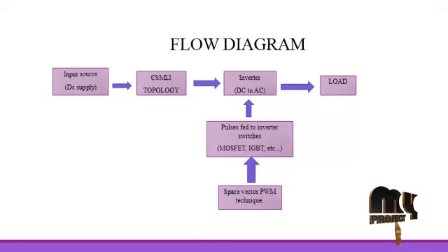Another main parameter in calculating the total cost of the inverter is the maximum amount of voltage blocked by the switches. If the values of the blocked voltage by the switches are reduced, the total cost of the inverter decreases, as is obtained using this proposed configuration.